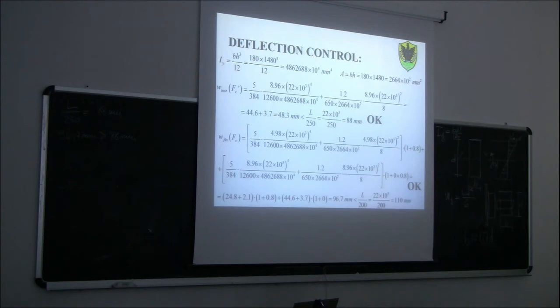No, what I'm talking about is if you need to recalculate the self weight. In this case, you are increasing either the depth by 4 centimeters, so from let's say 148 centimeters to 152, or the breadth from 18 to 22. Or to 20, so no, we said from 18 to 20. Are you going to recalculate the self weight again? No, you write down that there is a small increase in self weight.